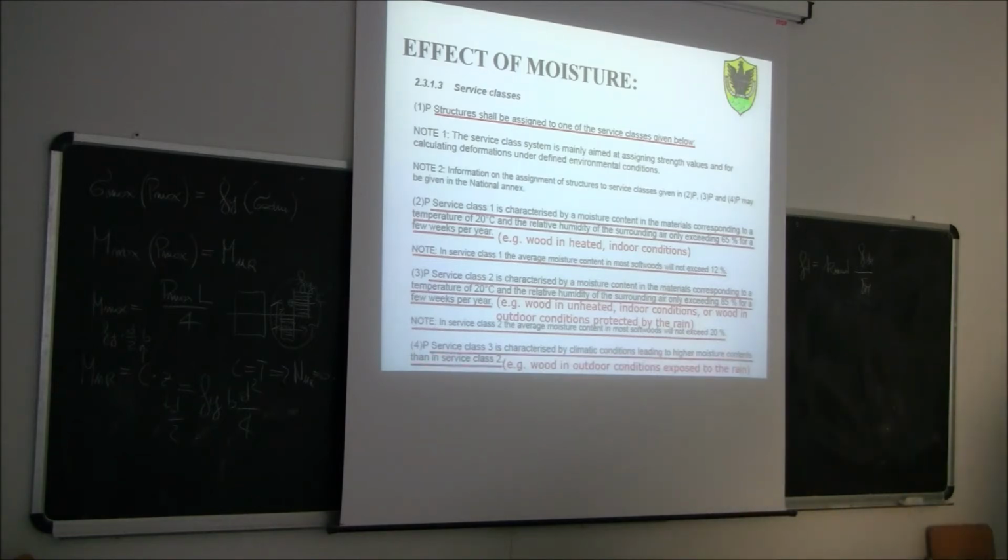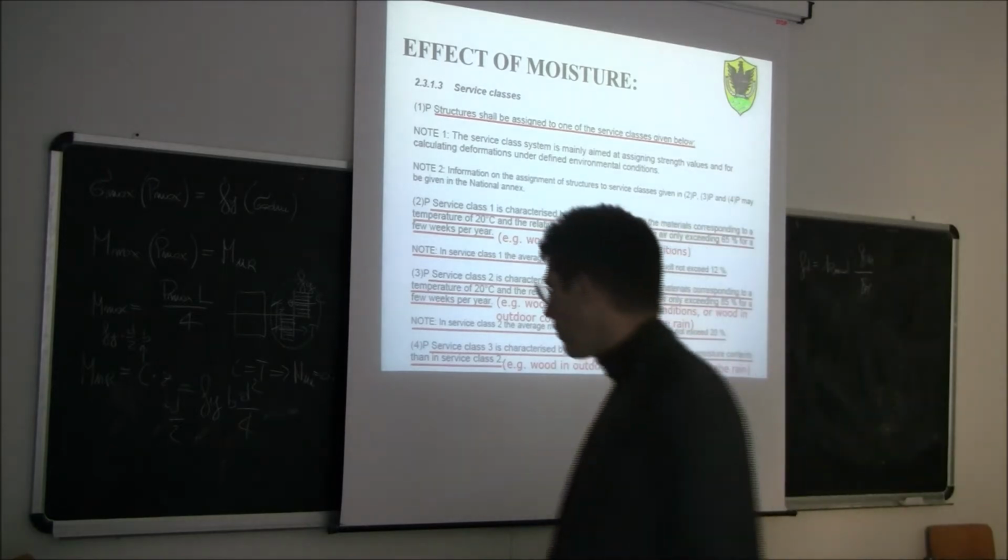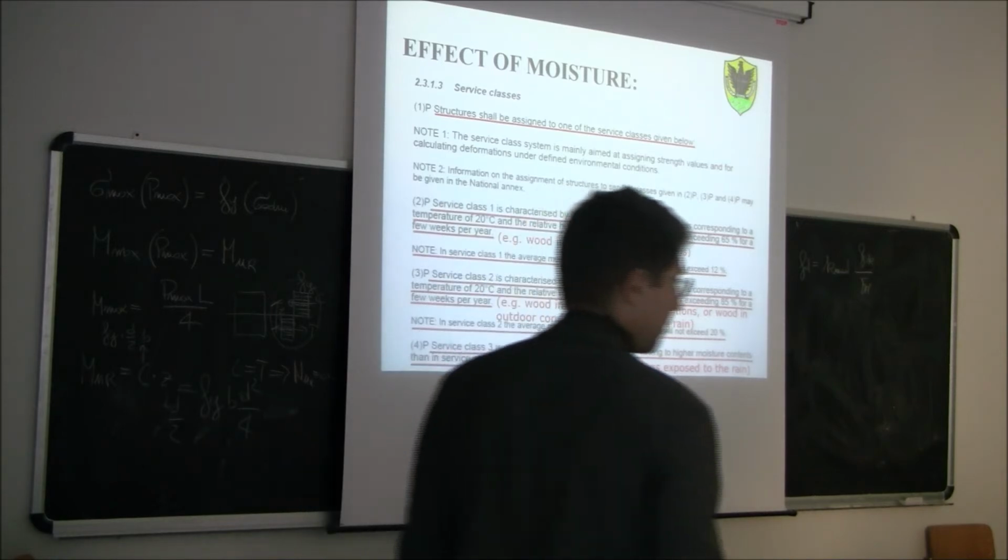Last but not least, service class 3. Service class 3 is characterized by climatic conditions leading to higher moisture content than in service class 2. So in this case, we get a moisture content more than 20%. This is obviously the worst class.